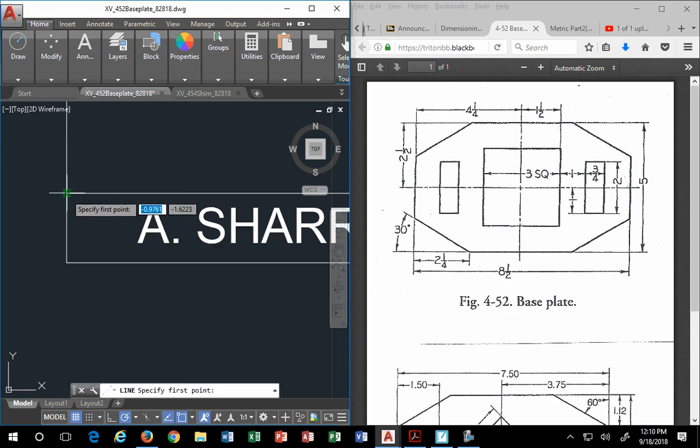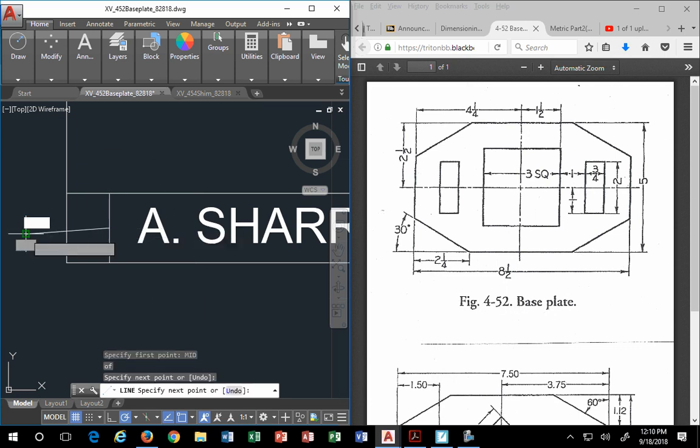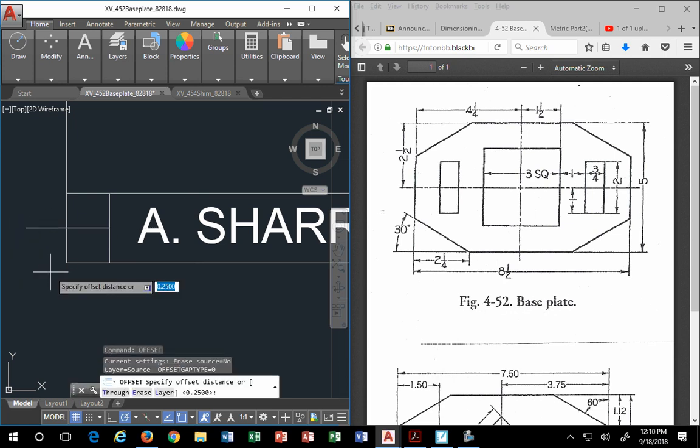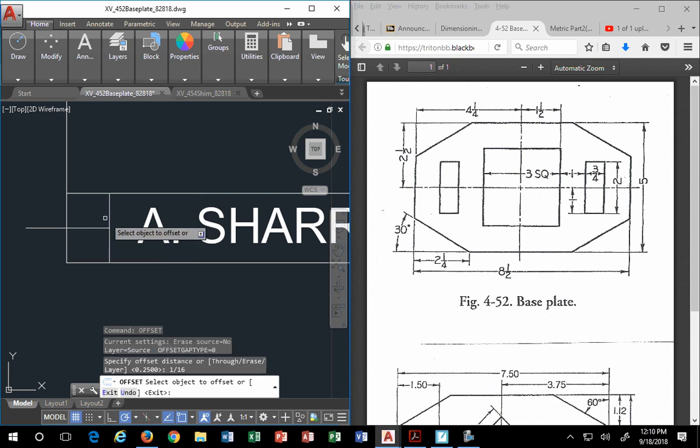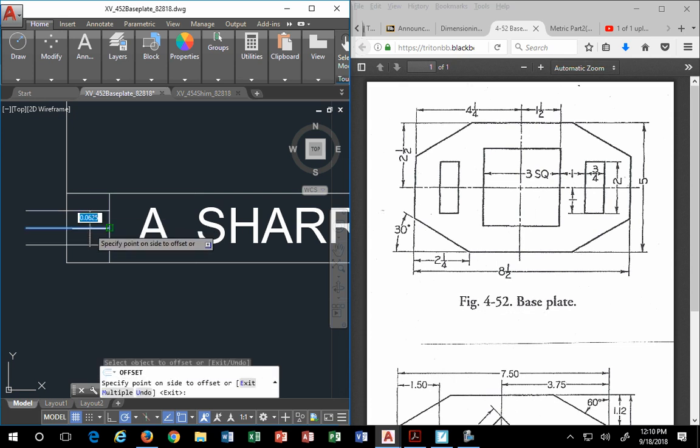For fun, let's just try to draw that from here to here. Okay. Then I got a line from midpoint. I showed you guys how to do that on the fly. Whoops, undo, horizontal. There we go. By offset, what's half of 1/8 of an inch? A 16th. So if I type in 1/16, I go up 1/16, I go down 1/16.